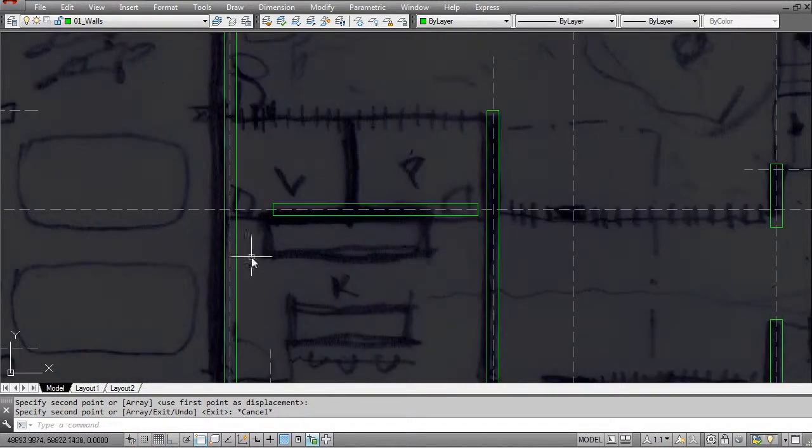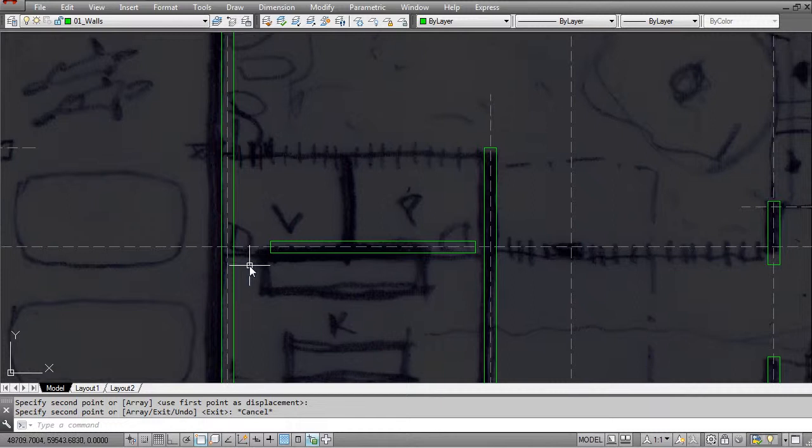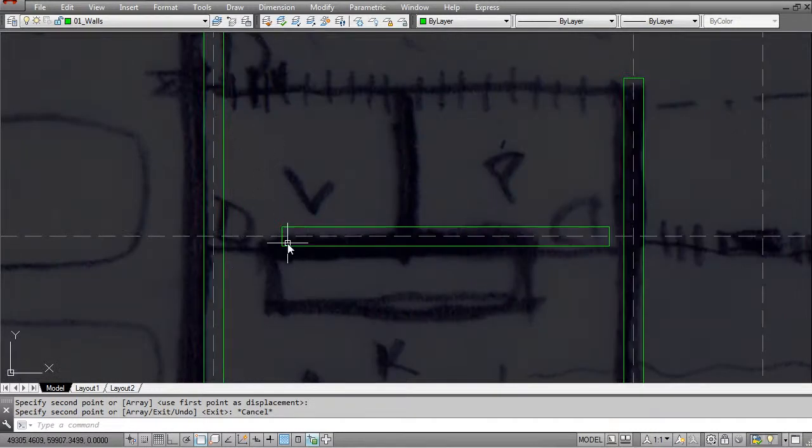Now you want to keep in mind that you have door openings on both sides. So you want to allow for sufficient space for that door, as well as space for people to be able to walk around. Remember, if you use your minimum dimension of about 900 millimeters for that door, with that table being in front of it, it's going to create quite a narrow space to walk through. Because this is quite a large house, I'm going to allow for 1.2 meters for that door and a little bit of space as an offset away from this wall, just so that there is enough circulation space.